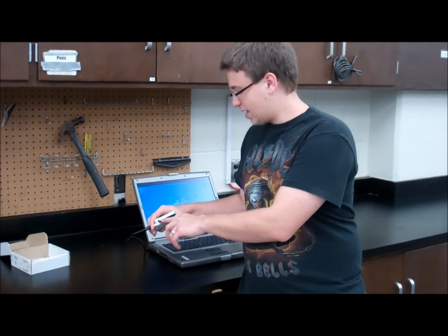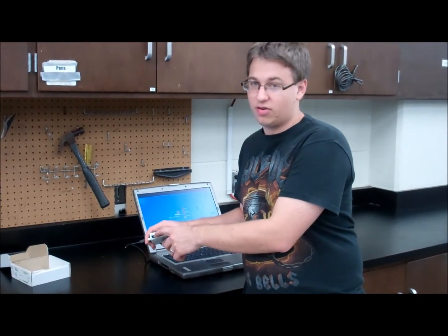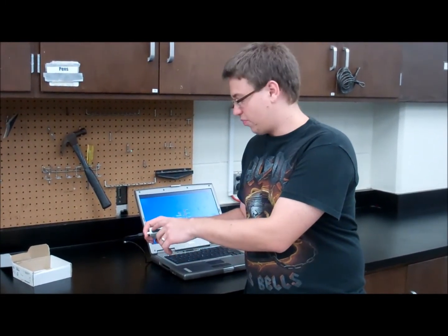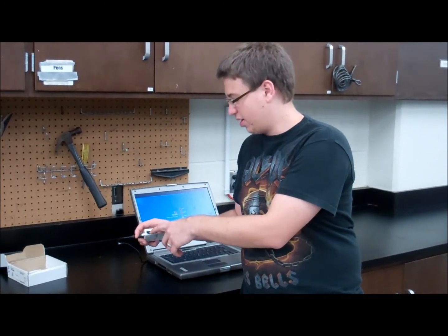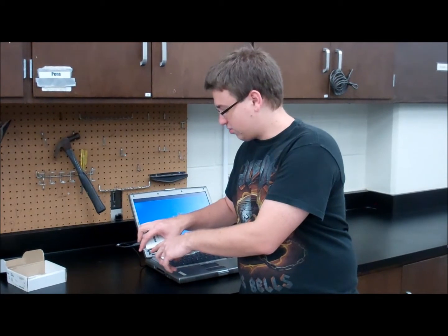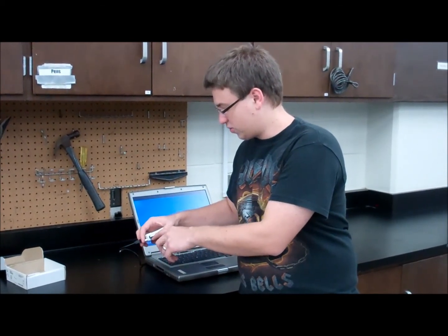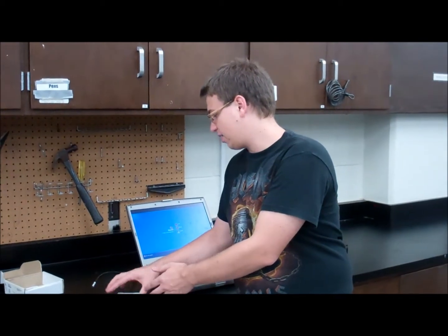You'll see a port that says AI0 plus and AI0 minus. In the plus port, you're going to put the positive input, and on the minus port, you're going to put the ground input. And you're going to take the set screws on the top here that correspond to those ports, tighten it down, and then you can start using the DAQ in LabView.